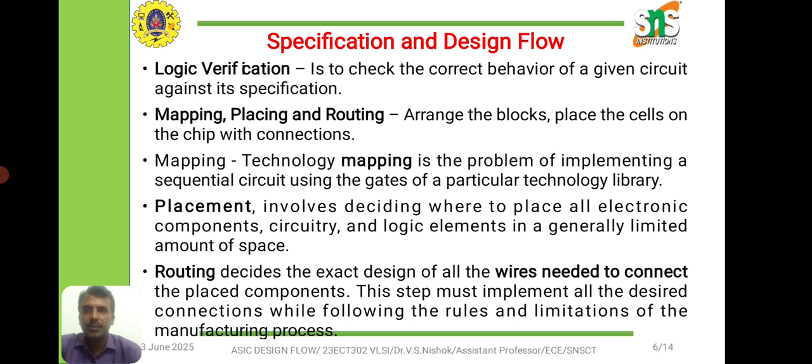And then placement represents placing the components efficiently to reduce the area and to reduce the power. So those parameters are kept into consideration with the help of the EDA tool, and the placement represents the placing of the components that is needed for our design. And then finally routing represents the wire connectivity between each and every component.